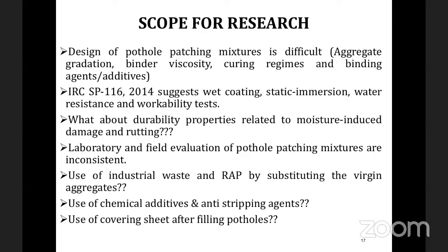So the first aspect is the design. As I told, it is one of the critical issues: which gradation we have to take, what binder, what should be its viscosity, what binding agents we have to use, and what the curing regime is. Here we can do a design of experiment for different aggregate gradations, dense or open gradation, binder (cutback or emulsion), curing regimes, and binding agents. You can take 3 and design the experiment through DOE, and then do the tests.